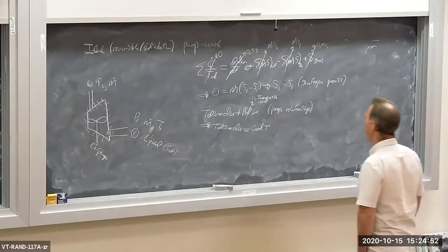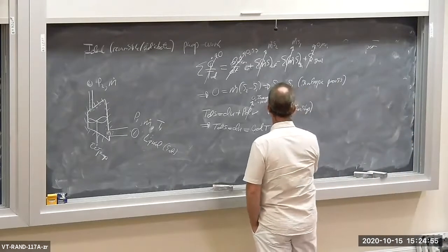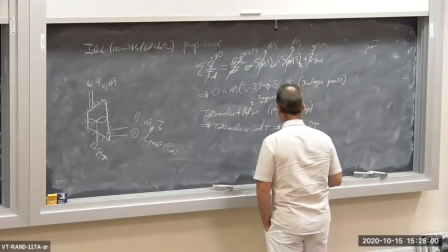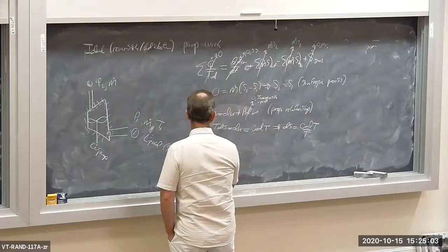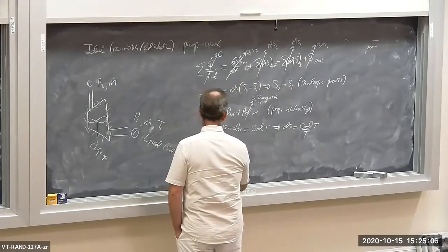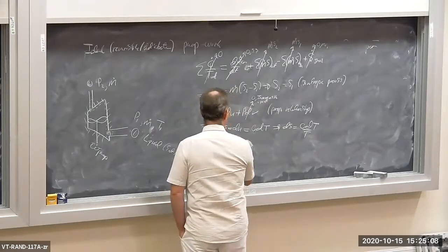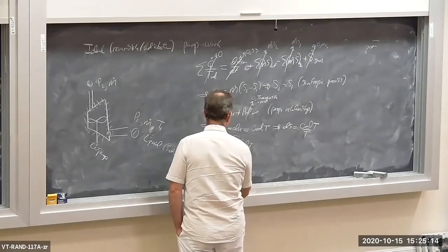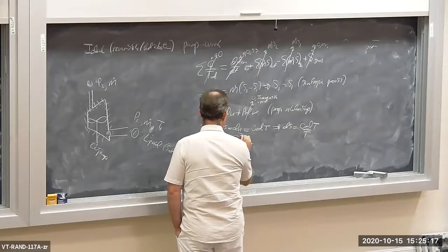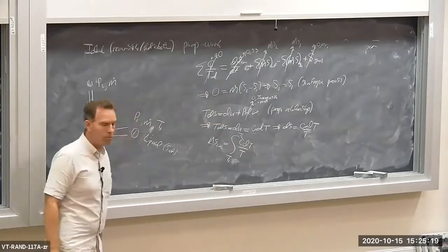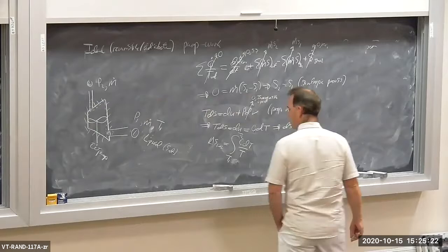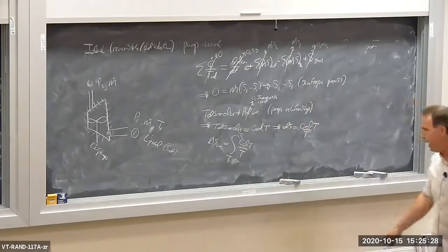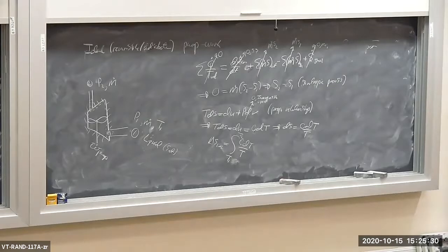Okay, so let me solve for ds. ds is equal to c dt over t, or delta s from 1 to 2 is equal to the integral of the specific heat dt over t from T1 to T2. Okay, so for this process with an incompressible, delta S is equal to integral Cp dt over T.